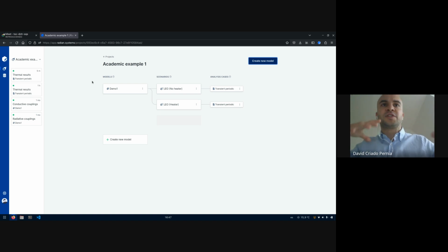And finally, you can configure a material, rename them, group them in parts, and eventually you just export the thermal model, and one of these models is created automatically in the tool. So that's how you can import a CAD file from SolidWorks, CATIA, AutoCAD, or any other CAD tool that you are using today.